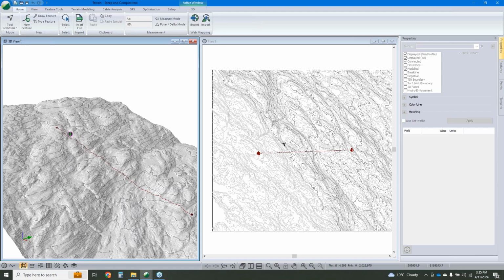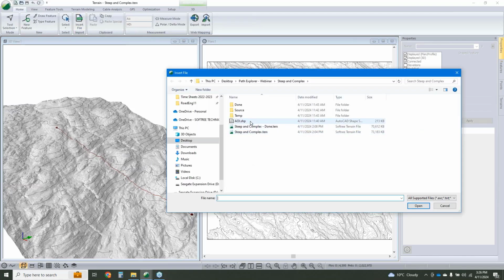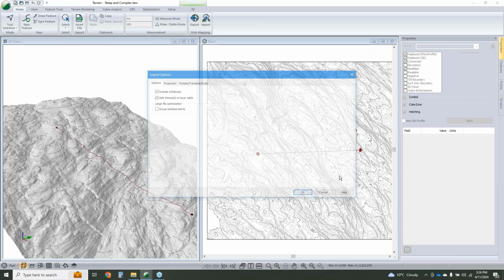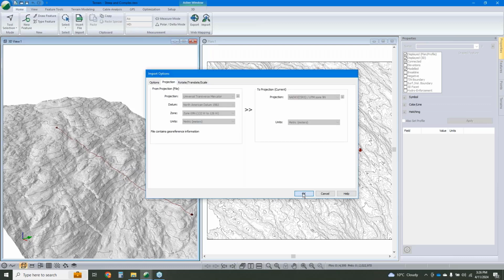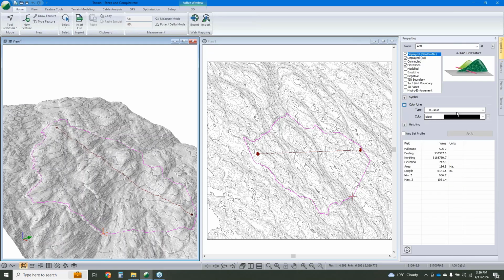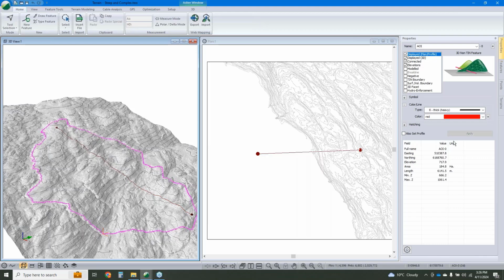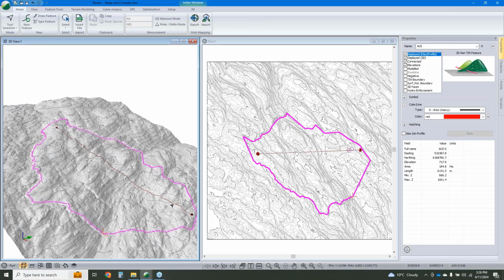Now, another thing that we can do here to help reduce the solve time is we can dump in, and we could draw it around too, but save watching me sketch, I'll bring it in as a feature that's already set up. We could say, well, we want to go from A to B still, but we want to set a no-go polyline to keep us within this feature.